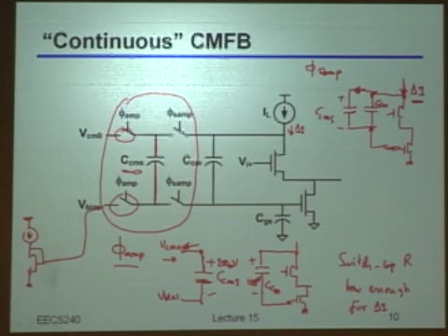Still, I need a small resistor, but I don't need that buffer anymore, which would bring me huge power consumption. I can implement a small switched-cap resistor because I can play with the frequency and the value of the cap, while at the other time I was obliged to use some buffering with a very small RO. On the other side, the glitches are much smaller because I'm saying it will take more time, but I will do this softly, right?